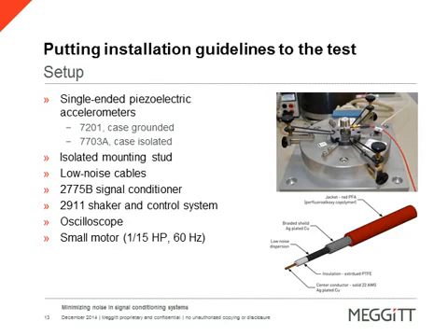With low noise treated cable, you typically get about an order of magnitude less noise, and that has to do with that dispersion layer, that black carbon graphite treatment you see over the Teflon dielectric, where you have the center conductor, the Teflon dielectric, and then this black coating. It is a conductive film that bleeds any charge buildup due to cable whip back into the shield of the cable, and that way it keeps it away from the center conductor or your signal.